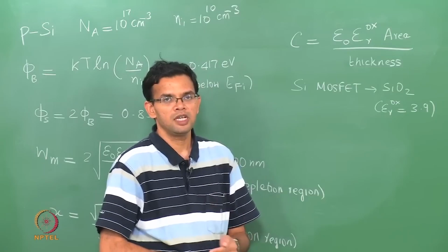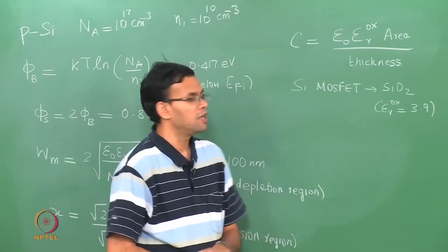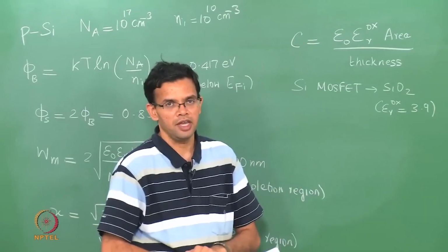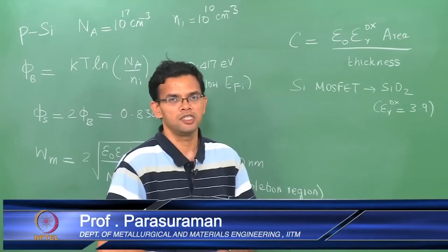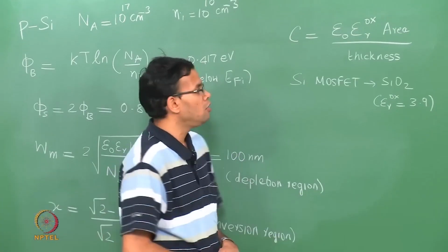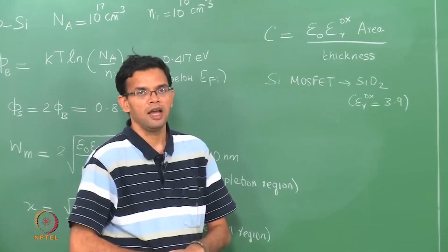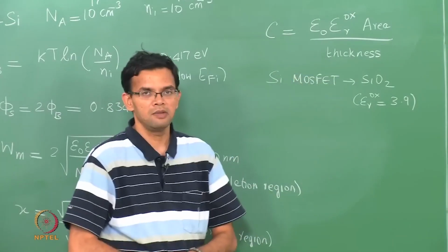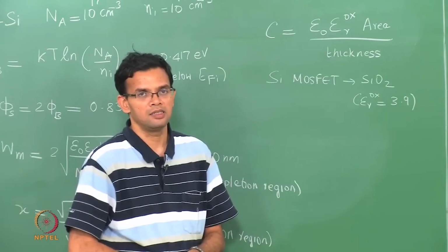But if your thickness becomes too small, the oxide layer is very thin, so that you can have tunneling between the metal layer, which is your gate, and the N channel, and this will affect the properties of the channel. In order to prevent that, the oxide layer is replaced by other high K dielectric materials, so you can still have a reasonable thickness while at the same time having a higher capacitance.